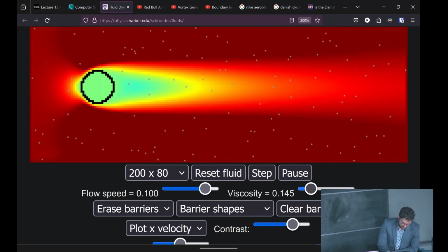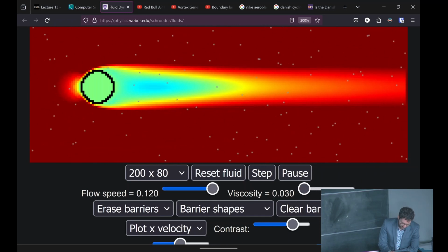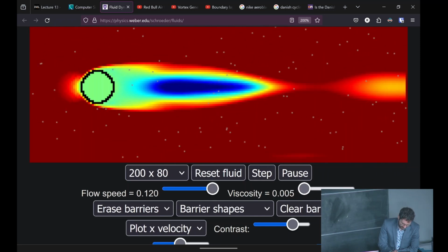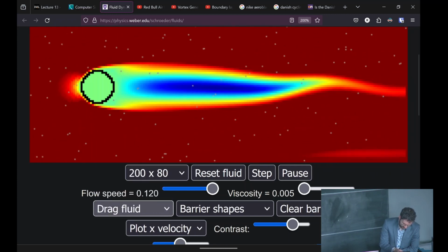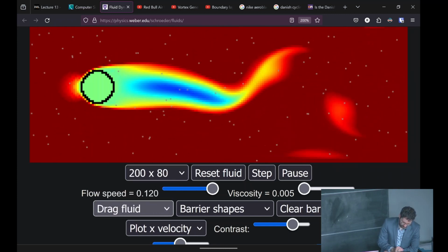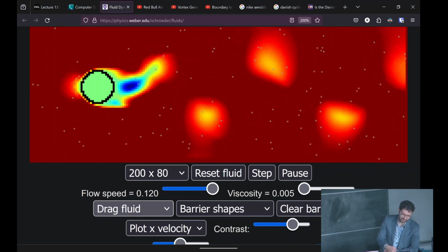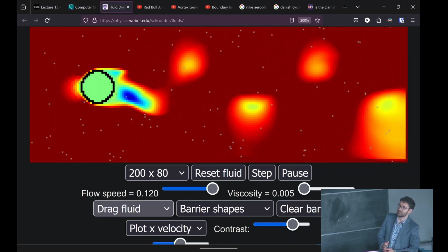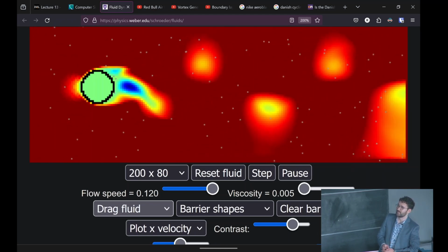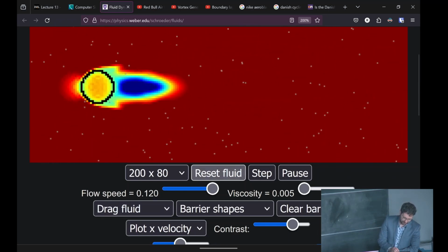But at a certain point, depending on the simulation, we would expect some unsteady phenomena to happen here. If I can drag this, hold it. This is all solved just running on my computer in the web browser. This is a numerical simulation technique called the Lattice-Boltzmann method, and it can run very fast for laminar cases. What happened there was really interesting. I'm going to reset the fluid.